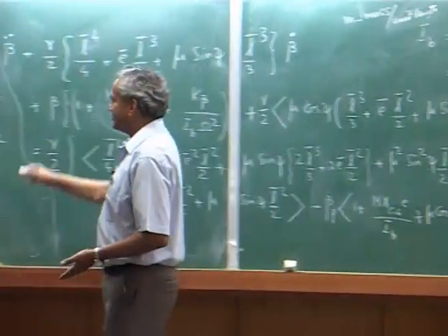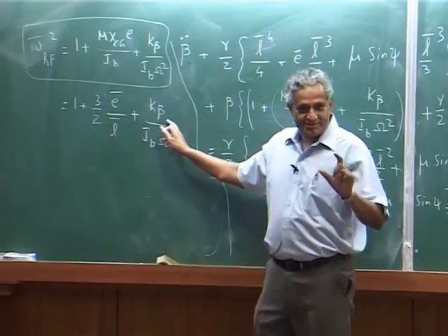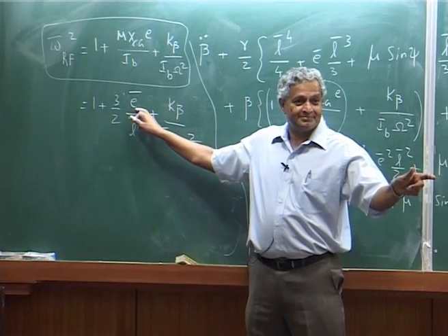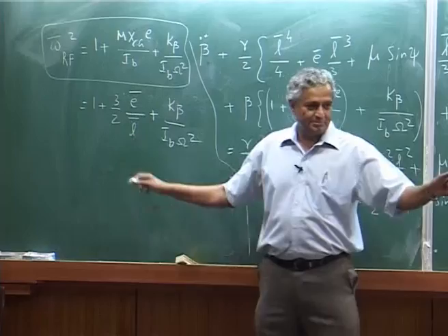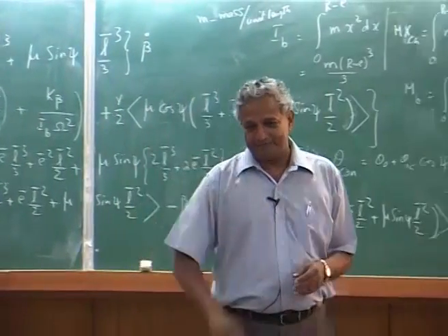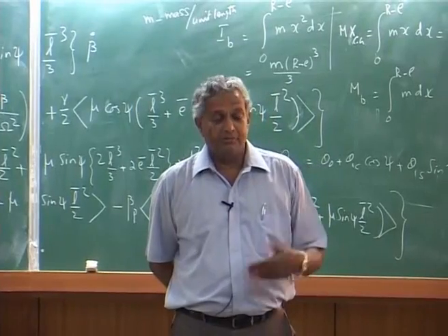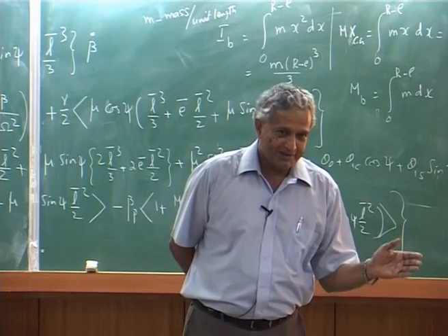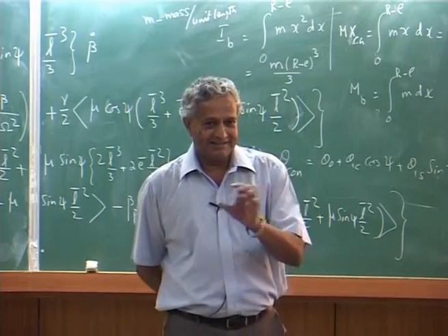But if I put a spring, I add one more stiffness term. So, you just see the root hinge offset gives us stiffness basically. Your flap frequency is more than 1. Now, how much? So, this is where the hingeless blade, articulated blade, that key difference.